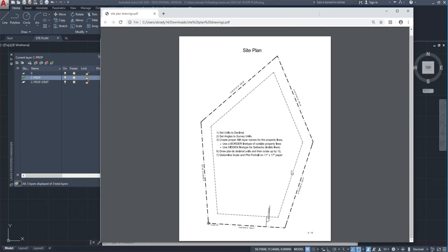And create this inner easement. And if I use a polyline and this entire site plan is one line, I can offset that in without having any cleanup necessary, okay? Because if I use the line tool to generate this and I offset it in, there will be pieces of line right here that we just don't know how to deal with yet, okay?